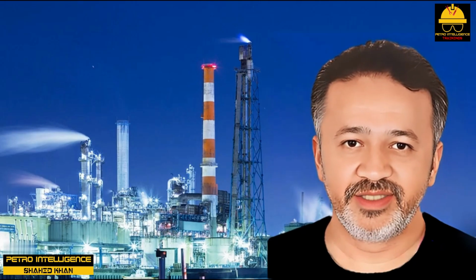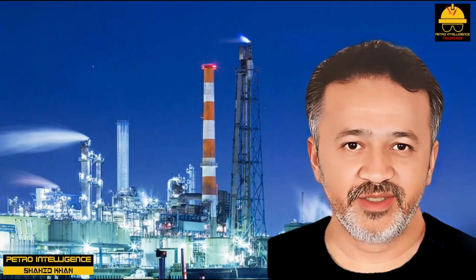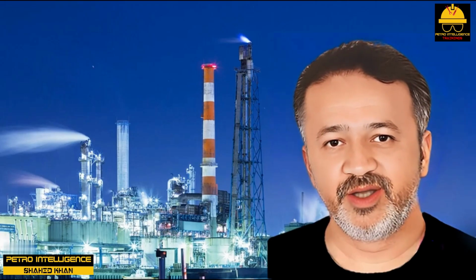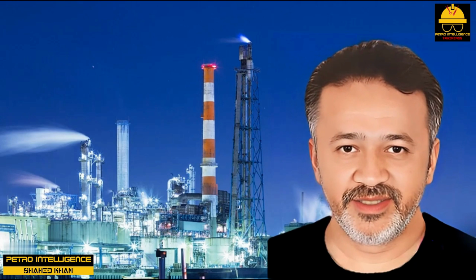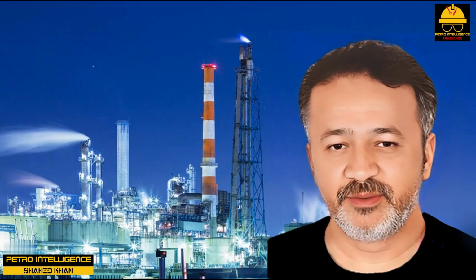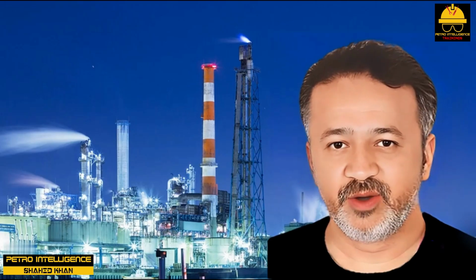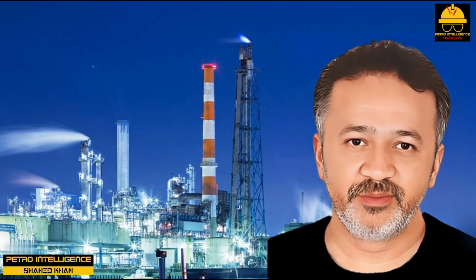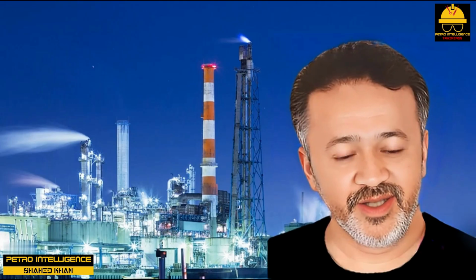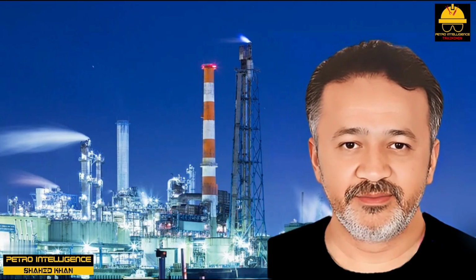This makes it more difficult to liquefy the refrigerant vapor. The vapor is then forced to condense at a higher temperature and pressure. Of course, this raises the compressor discharge pressure. And, as we have discussed in the lecture, this increase in compressor discharge pressure invariably reduces the compressor's capacity and may also increase the horsepower needed to drive the compressor. An increase in the elevation of the receiver will reduce the pressure of the liquid refrigerant. This loss in pressure due to increased elevation will also require an increase in the surface area of the condenser devoted to subcooling.